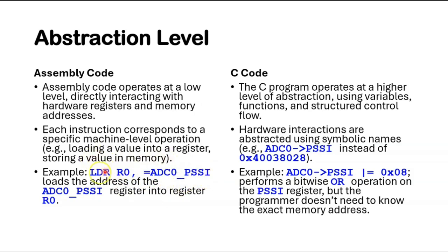What this means is it loads the address of the ADC0_PSSI register into register R0. ADC0_PSSI has been assigned a hex address at the start of the program.